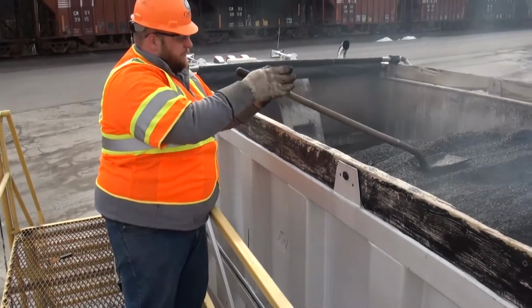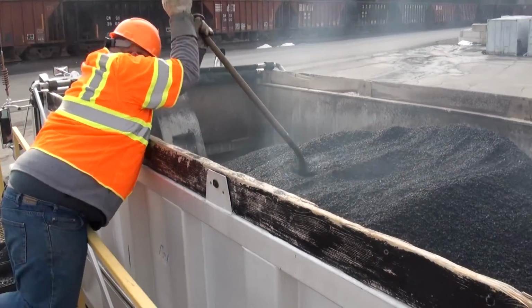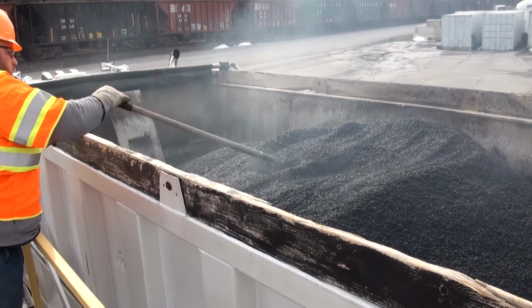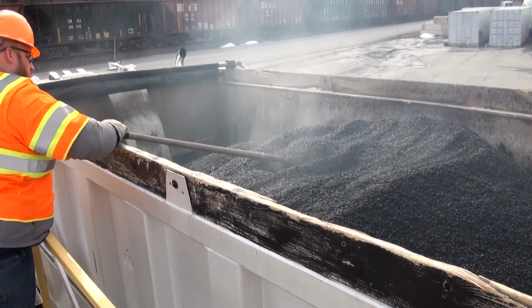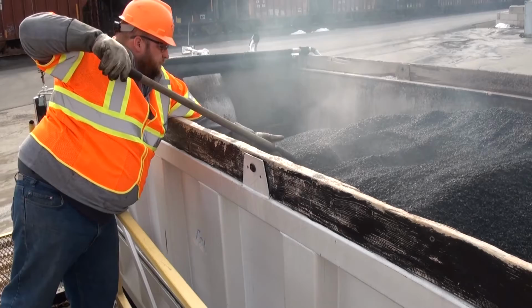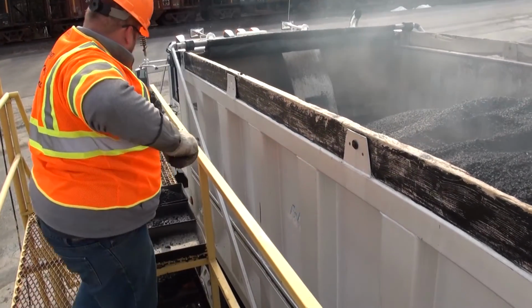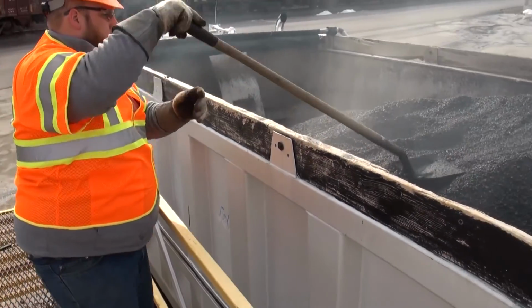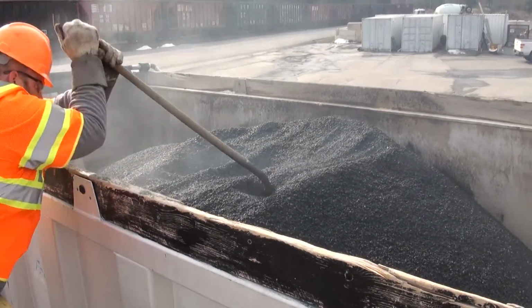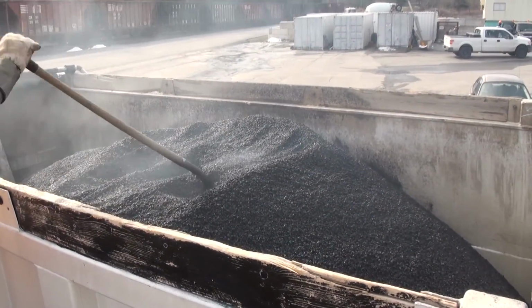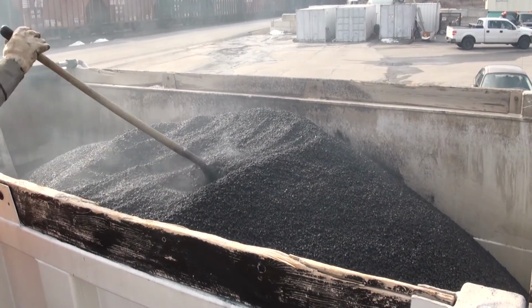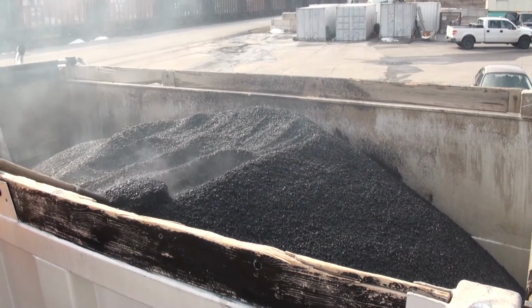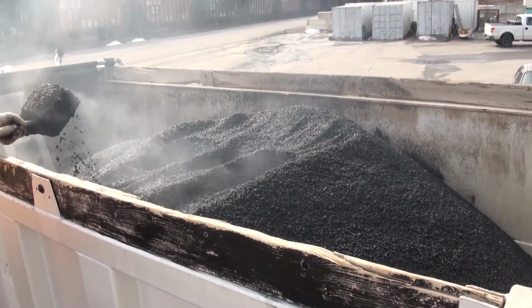So here the technician is. Previously he took the shovel full in the middle. Notice now he's on the left side. He's taking the shovel full here, with a little space in between the previous shovel full. He's making sure he's not letting where he's taking his sample segregate back in that area. And he's taking them from different locations across the top of this platform. This is to ensure he gets a good representative sample to do his volumetric testing.